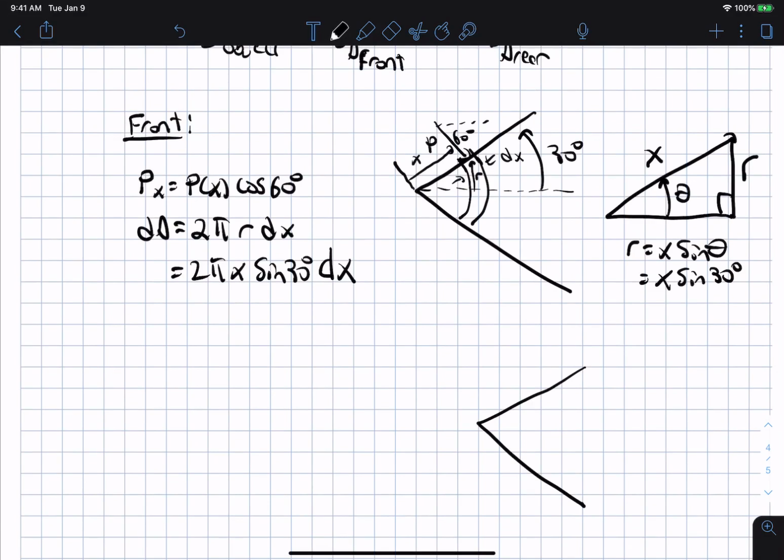Okay? And then on the surface, we have a pressure, and it is linear, and we know that at the tip of the cone, the pressure is maximum at 1/2 rho u squared. P0 equals 1/2 rho u squared, and this is the end of the cone at the top, and I'll call this length L, and P of L equals 0.